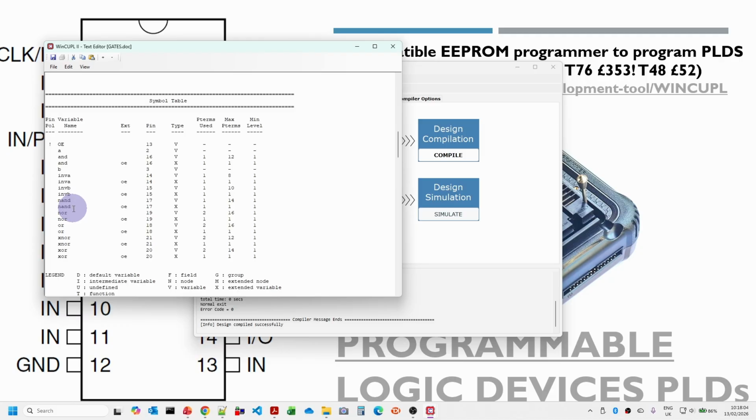So these names are case sensitive, and if you accidentally put a capital N in there or something like that, you might find that there's a zero or a gap there, and that would indicate it's created another term here, and you probably are going to end up with problems with your PLD. So look for any gaps here. There are circumstances where gaps here are okay, particularly if you're using fields and things like that. But in general, when we've got a simple one like this, if you've got a label here without a pin assigned to it, it probably means you've got a typo somewhere.